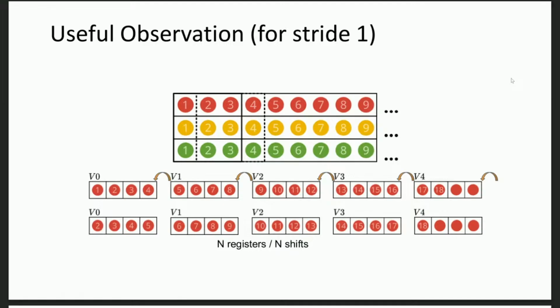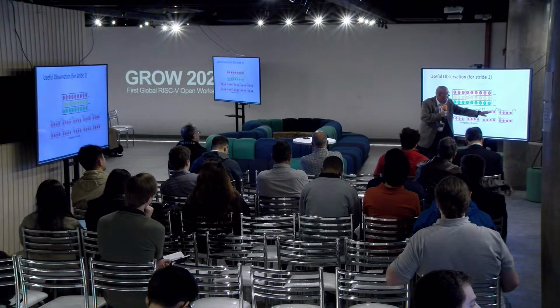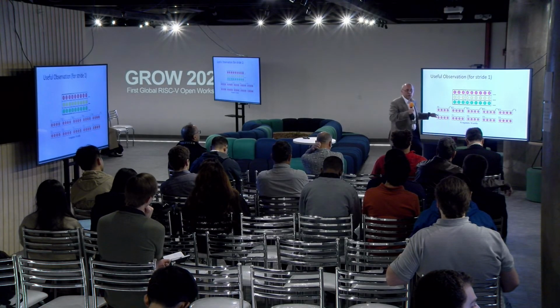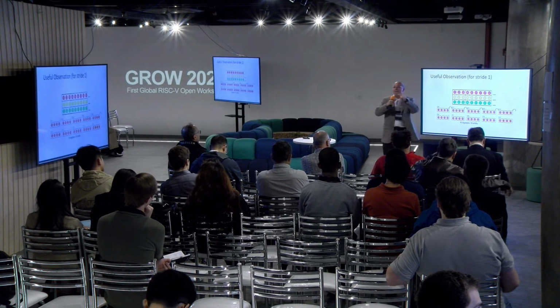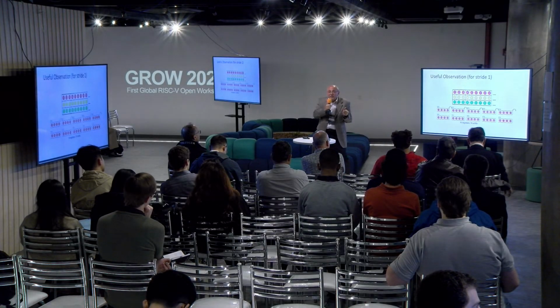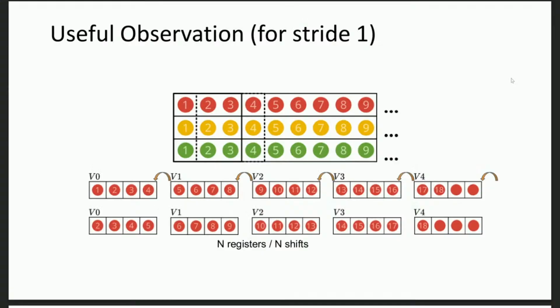So what we did basically is, in the Power 10 MMA architecture, you have all these vector registers. And they have something similar to the VLEN in the RISC-V architecture. You can replicate instructions to do similar work with many vector registers. So basically, they have an instruction in which you can lay out all the data and do a shift, connecting vector registers. A full shift with all these 4 vector registers will result in the packing for the next window. And you do that inside the processor. You don't need to take all this data from memory and write it back, storing it into memory, paying the price of the latency to go into memory. You can do that inside the processor.